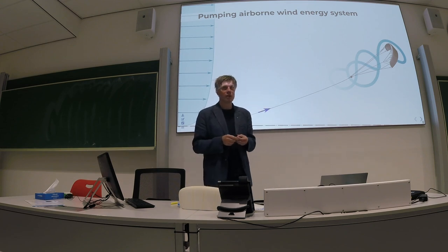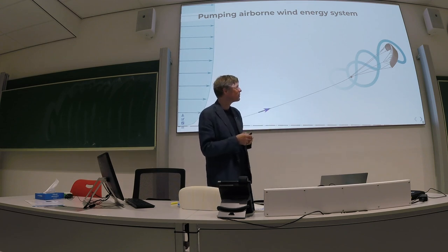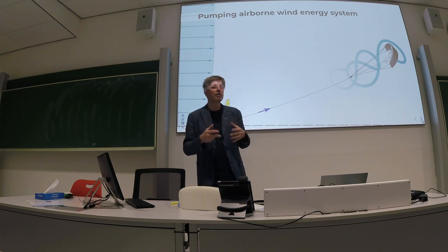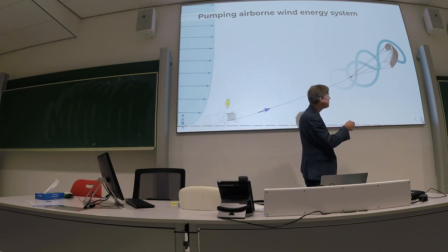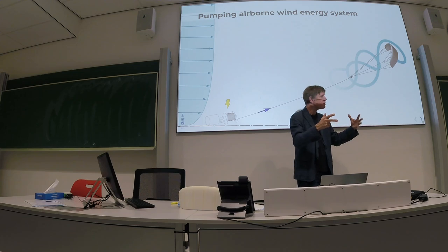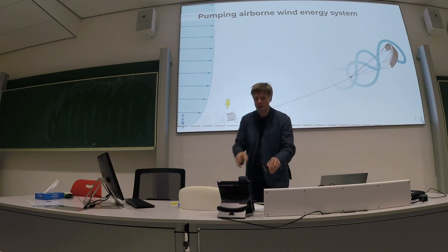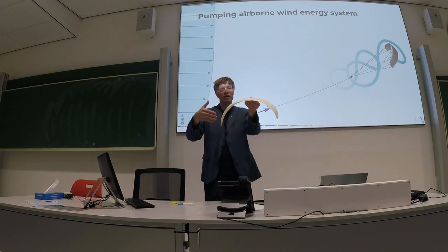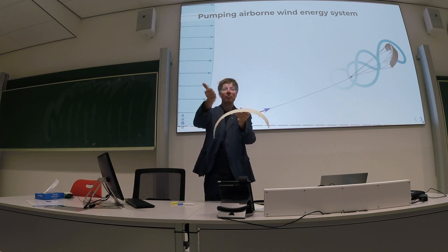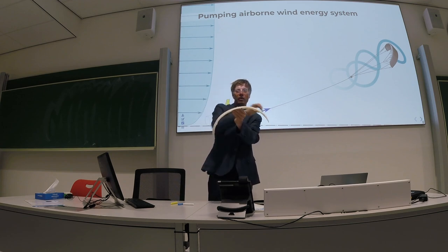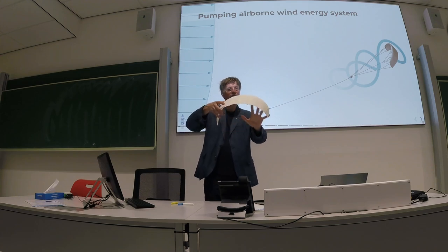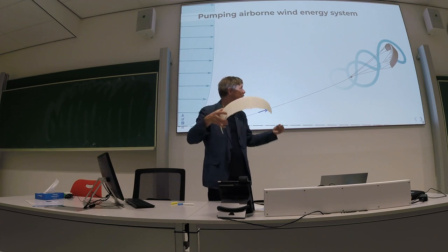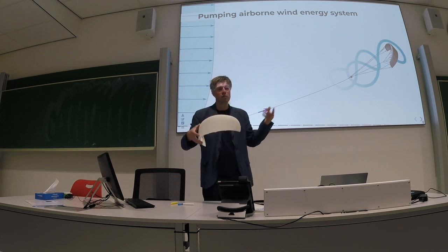And the trick is that this wing here is inflatable, meaning you can pack it very small, and it's actually kept in shape by the aerodynamic suction pressure. So when it flies, there is a suction pressure here on the upper canopy that pulls it in shape against the restraint of the bridle lines that connect it to this control unit. This is how it works.